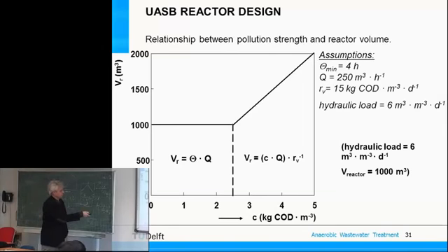So, despite the fact that you're lowering the concentration of the incoming flow, there is a minimum volume below which you cannot go with the reactor volume, since then the hydraulics are limiting the volume. And so to speak, every anaerobic reactor is therefore determined by 2 calculations in calculating the volume. One is calculating the volume in relation to the organic conversion capacity, and the other one is the volume in relation to the hydraulics. And this is a minimum HRT, so the volume can drop down, and then we have a fixed lower volume.